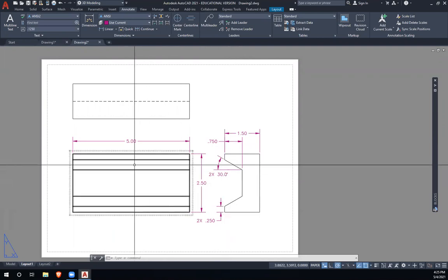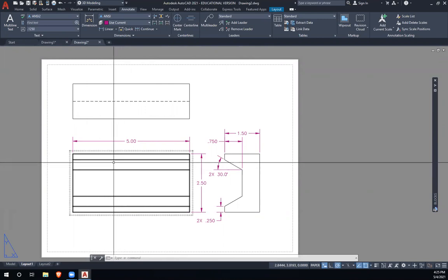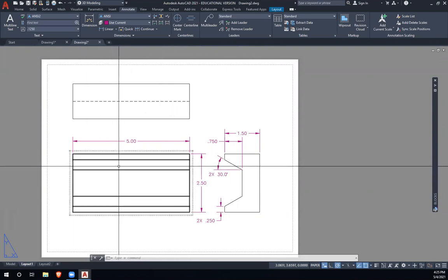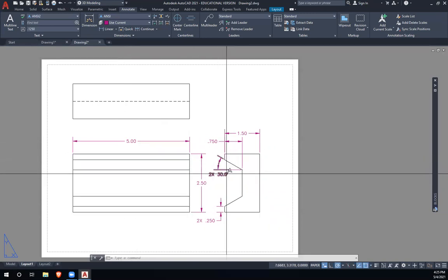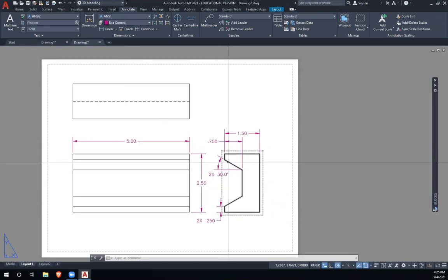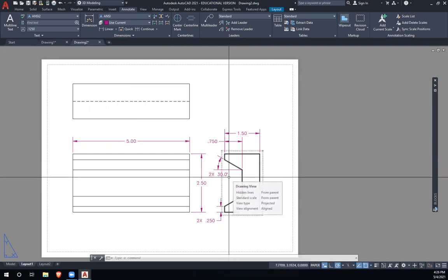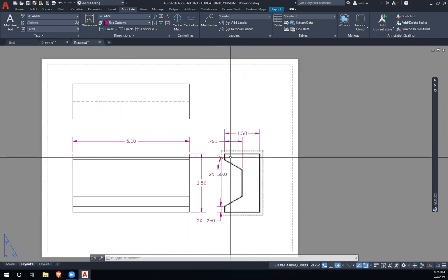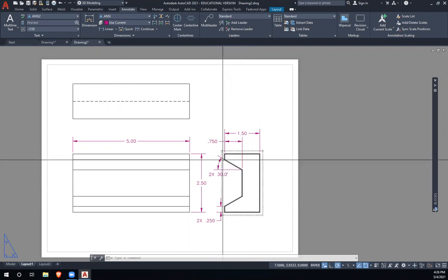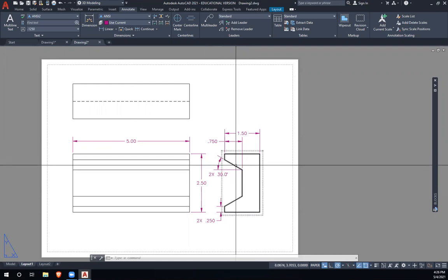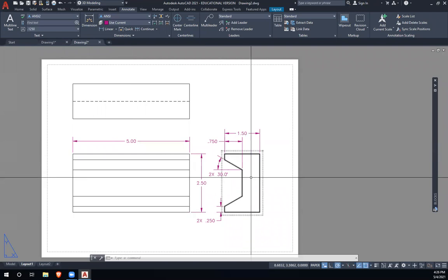It'd be really awkward to put like a 30-degree dimension on the front view because I see that surface, but that'd be really hard to show that. But it's much easier to show it where I see the angle itself, right? So the overriding principle there is where I see the shape of it. So I see the edge of this.